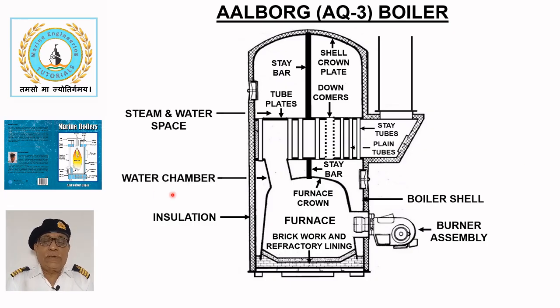The space around the furnace forms the water chamber, and the water level is maintained above the top tube plates, ensuring that the tubes remain full of water to prevent their overheating. Steam is collected in the dome above the water level.